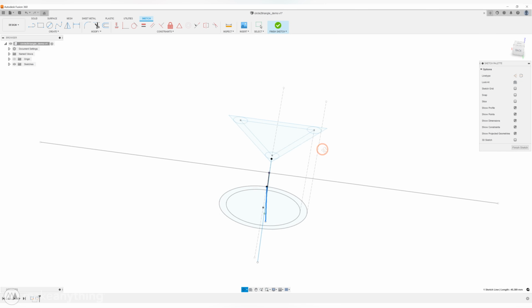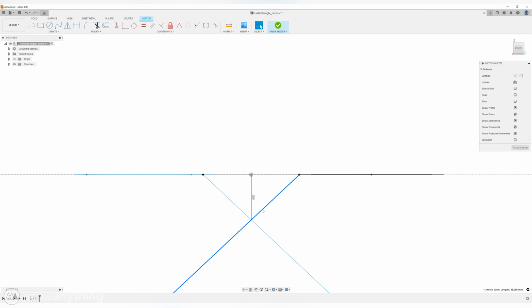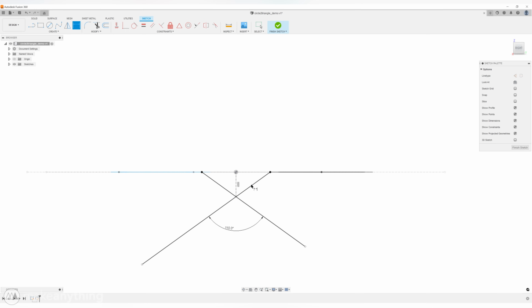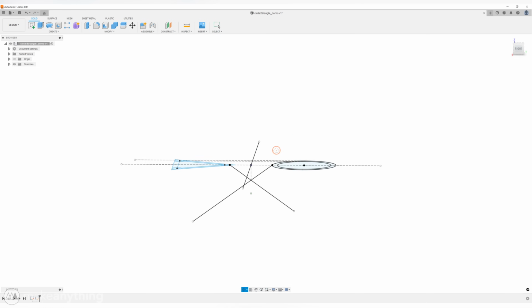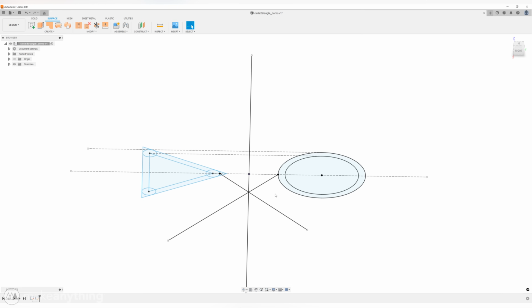These crossing lines actually represent the viewing angle for our illusion. So you're welcome to play around with it, but I've found that 110 degrees here works well. That's it for this sketch, so we can hit Finish Sketch, and now it's time for us to switch to the Surface toolset. Most of my work is generally done using solid modeling, but surfaces can be really useful for building weird and complex forms, like these ambiguous shapes.